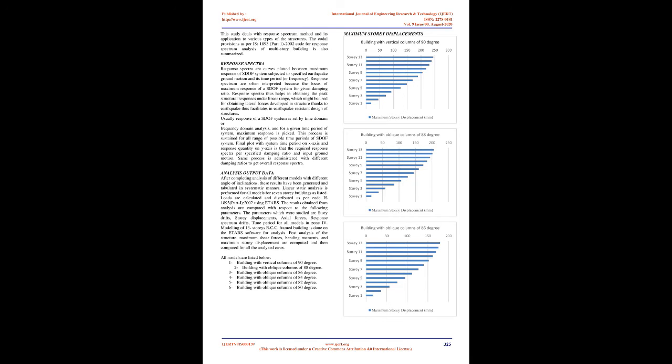A whole modal analysis defines the history of responses. The whole history of responses is needed for designing. The strategy used to attach the results in the response spectrum method is more critical to get accurate values. Within the analysis, when every effective mode is used, then an acceptable technique is needed for combining the results. The square root of sum of squares method is mostly used, in which the squares of all results are summed and then the root of the result is taken. And the most accurate technique is CQC, complete quadratic combination, in which the spectral results use damping and the weight ratio of relative frequencies.